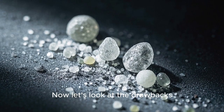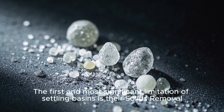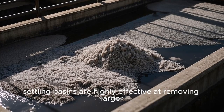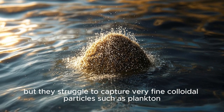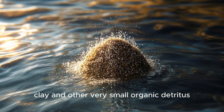Now, let's look at the drawbacks. The first and most significant limitation of settling basins is their solids removal. As discussed earlier, settling basins are highly effective at removing larger, heavier solids, but they struggle to capture very fine colloidal particles such as plankton, clay, and other very small organic detritus.